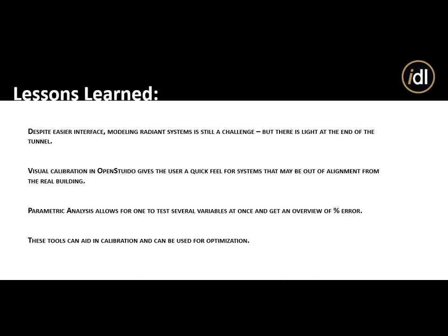So design constraints within OpenStudio. Trying to understand that a little bit. One of the design constraints is that you don't have functionality for walls, and I know there have been some issues on the radiant ceiling panels, but they do have the option where you're defining that coil that can be for heating or cooling, that you can designate that as either a ceiling or a floor slab.